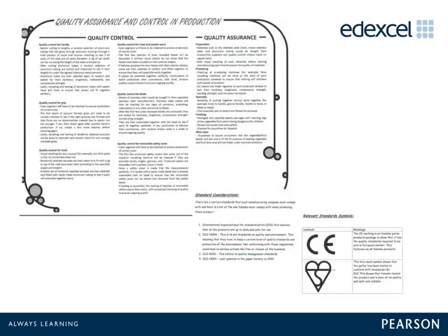The final section in product investigation focuses on quality. To meet assessment requirements, students must describe a range of quality checks carried out during manufacture of the product, specifying what the checks would be, how they would be carried out, using what equipment. A quality assurance system should be designed for the product, and this could take the form of a flowchart, for example, using headings such as preparation, processing, assembly, finishing, and after-sales.